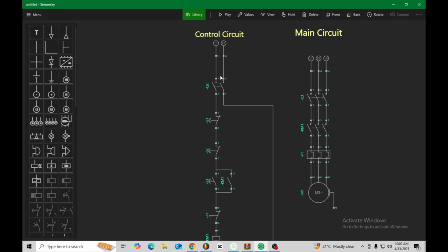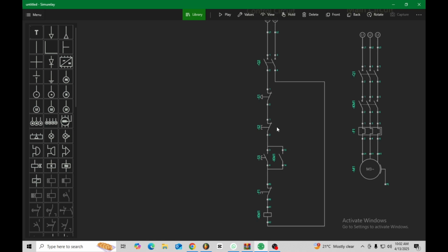But anyway, we have 2 circuit breakers. We have a double pole here and a triple pole over here. On this side, we have our emergency stop. As you can see by the look of the symbol, this is the emergency stop. So if there's any problem, anything that you notice going wrong with the motor, you click that in, and then it would disconnect the connection, and your control circuit will be unable to power or energize the coil in the main circuit. So this is an emergency stop. Always have one, always put it on. Highly recommended. You'd be good as daisies with that.